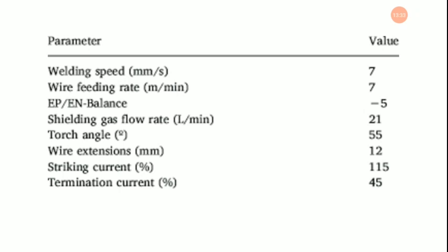So now coming to the effect on back width. The back width was considered as the quality characteristic with the concept of the smaller the better. The average values of back width for each parameter at levels 1 to 3 for raw data and SN data are plotted. And from the diagram, it clearly says that peak current, welding speed, and pulse on time are the most significant process parameters compared to the other process parameters.